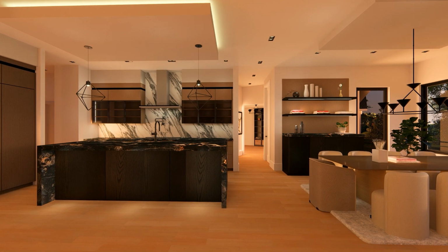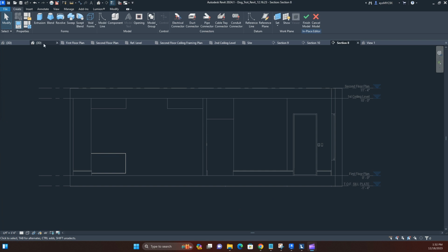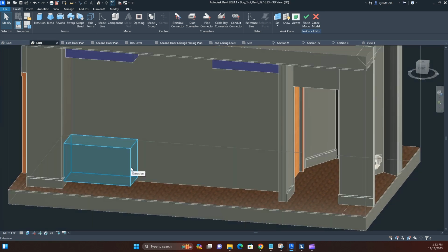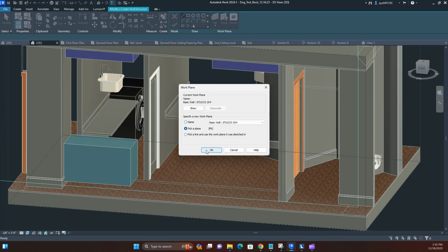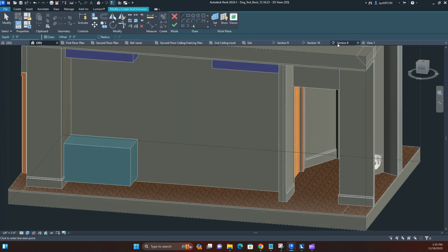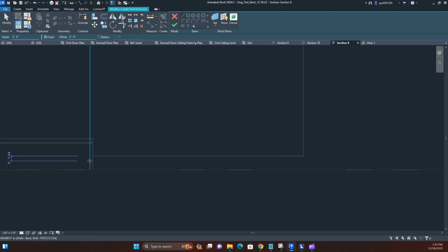I use generic model to create the kitchen soffit. These are extrusions and I use them for the base cabinet too. So the next step is to create a void form on the base cabinet to simulate the part of the cabinet that's right next to the wall that doesn't open. So I use create void. I draw up a line.